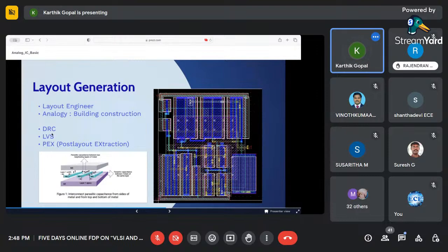If these criteria are met, let's say two lines should not cross each other, that is one of the criteria from TSMC, for example. They give a set of rules on how to design the layout. Once you do a layout, you do a DRC, design rule check. Each foundry will give you this design rule check, and we need to pass it. Only then can they guarantee the proper output. And what is LVS? LVS is layout versus schematic. You do a schematic, and the layout engineer does a layout. Each should match. That simulation is called LVS, layout versus schematic.